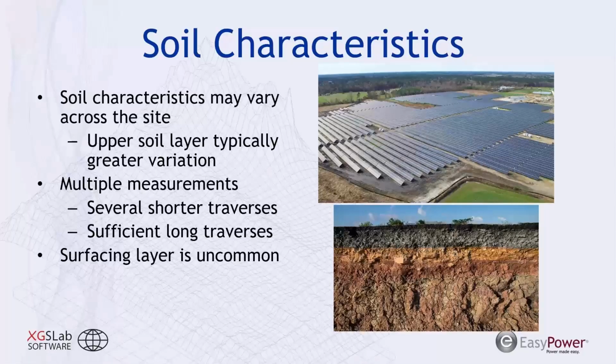For those that do grounding system analysis, as you might know from IEEE Standard 81, you also need to understand the soil characteristics at deeper layers, because even though your grounding system may not directly connect to those deeper layers, that has a direct effect on your system voltage, your ground potential rise that occurs, as well as your system impedance. So a challenge with these very large systems is getting a sufficiently long traverse to be able to characterize those deeper layers that drive your system impedance.